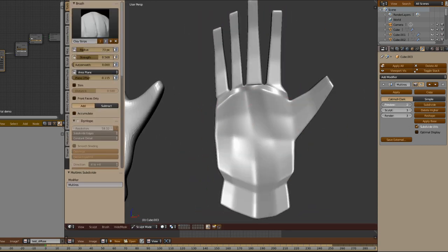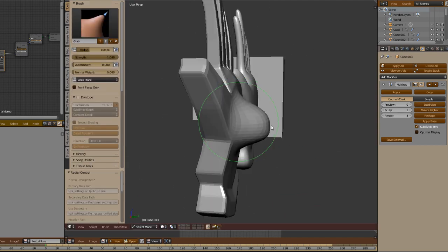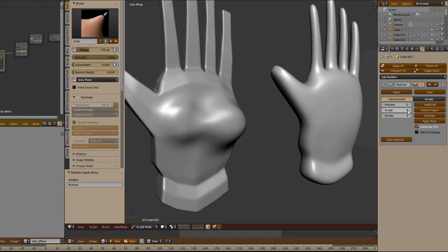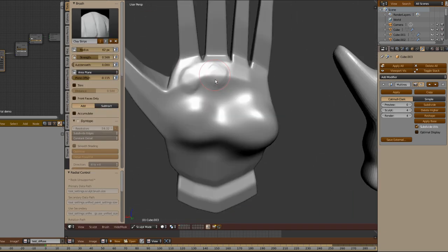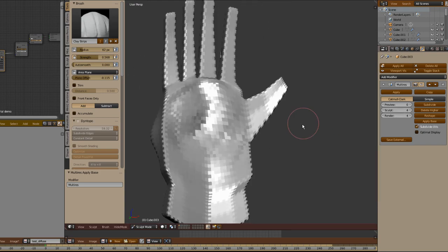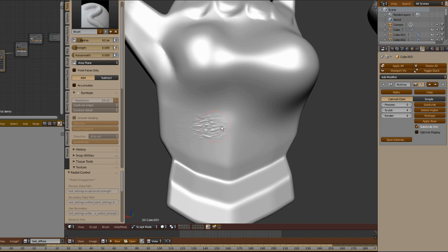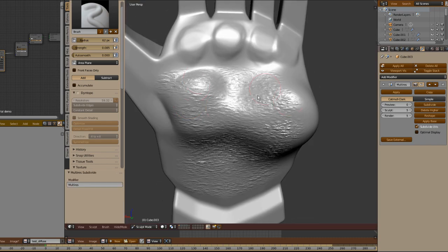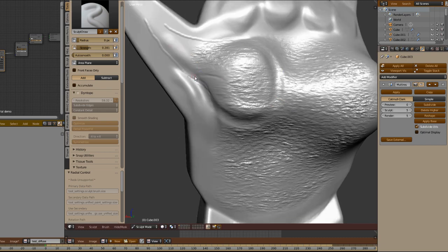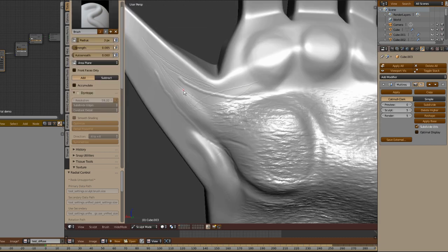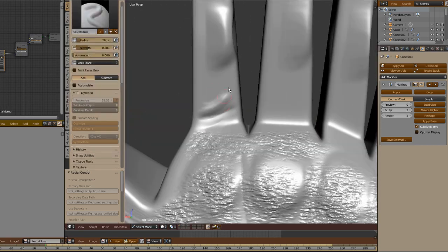The great differential of multi-resolution is that it provides users with different levels of subdivisions that remember changes made from one level to another. You can move up and down the levels of subdivisions freely and at any time. Changes made at low levels will be propagated to high levels, and details made at high levels will be maintained when the user goes down to the lowest levels. This type of system is widely used to generate displacement maps, bump maps, and normal maps.